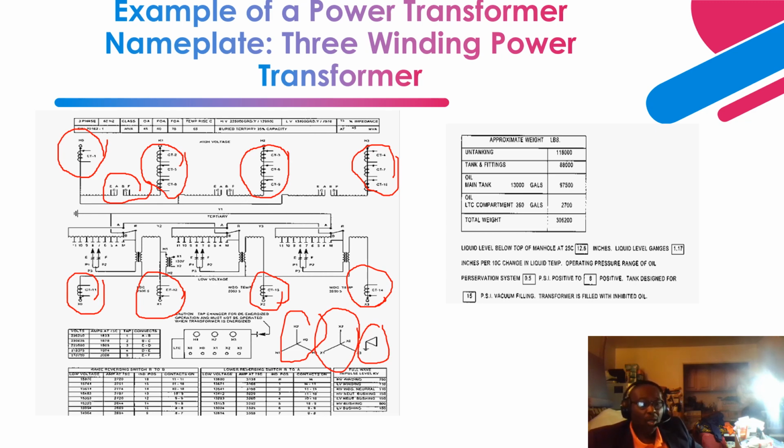And the on-load tap changer utilizes basically a preventive autotransformer, which is more of a reactor, to achieve all the tap positions in the load tap changer compartment, to vary the load side voltages that are to be utilized by the load. So this is all shown over here.